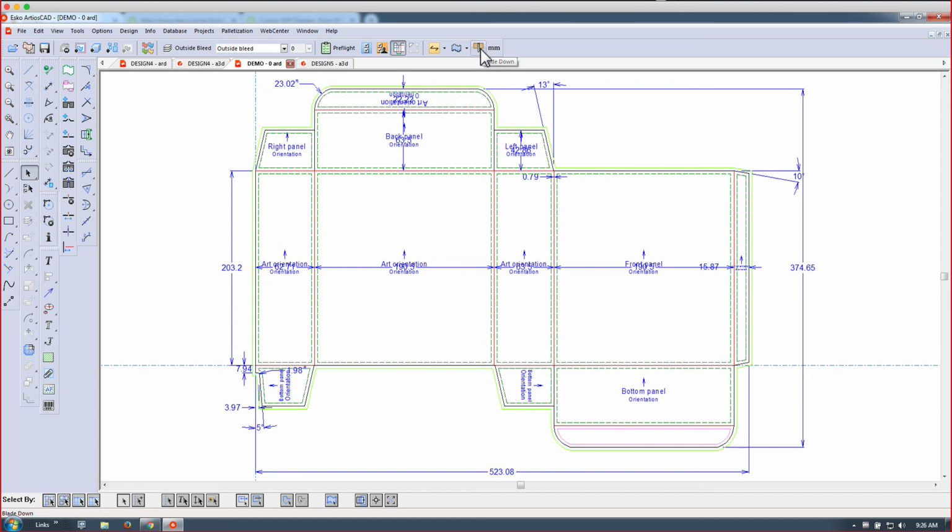This one here, blade down or blade up, is more important for Kongsberg cutting table design, where you can see what your design looks like, especially with very thick foam or reboards, you know, V-shaped notches that you create in there. You can look at that from the top or from the bottom.